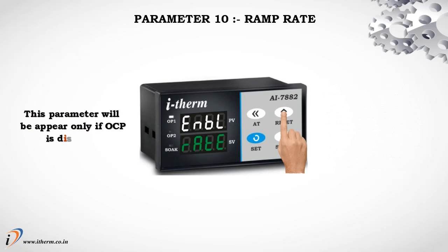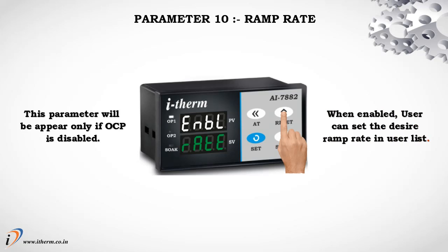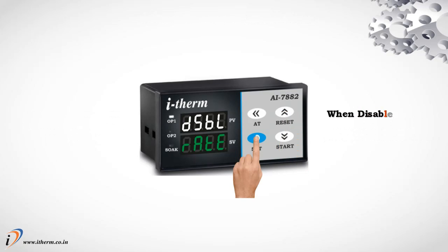Parameter 10, Ramp rate. This parameter will appear only if the overshoot control point is disabled. When enabled, the user can set the desired ramp rate in the user list. When disabled, this parameter will not appear in the user list.